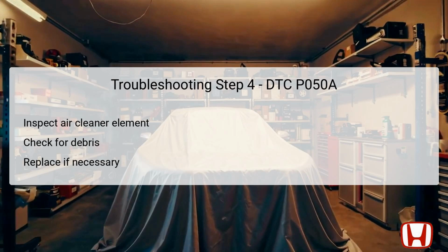Ensuring proper air intake is vital for the accurate functioning of the IAC system. After replacing the air cleaner element, technicians should carry out repair verification once again to ensure that the system is operating correctly. A clean air cleaner element is essential for smooth engine operation and effective idle control.